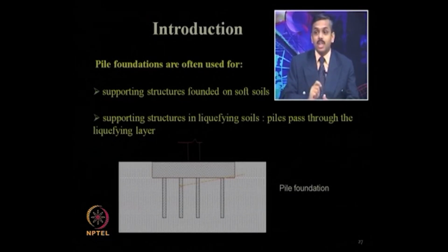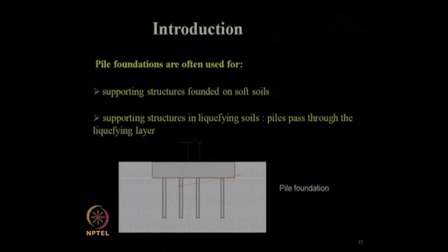So, this is one of the major criteria why the pile foundations fail in several earthquake conditions around the world, in big earthquakes, including the various Japan earthquakes, even our Indian earthquake also. During the Bhuj earthquake in Ahmedabad, several buildings collapsed and the pile foundation got damaged. Even earlier, in the introductory lectures of this course, I have discussed that for the Niigata earthquake, for the Kobe earthquake, various earlier Japan earthquakes, several pile foundations failed, right.